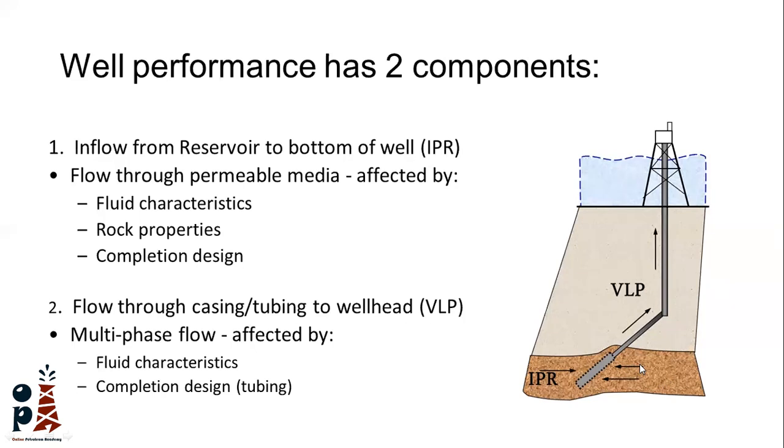A highly viscous fluid will experience more pressure drop compared with a less viscous fluid. So, as we will see later, it's important to do accurate simulation of the reservoir fluid, which can be done through data from analog wells in the reservoir.